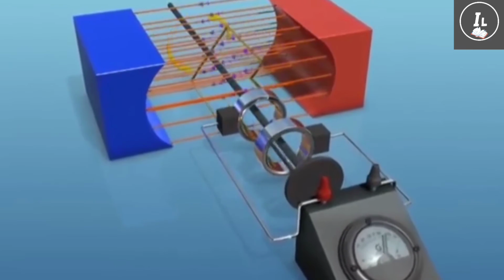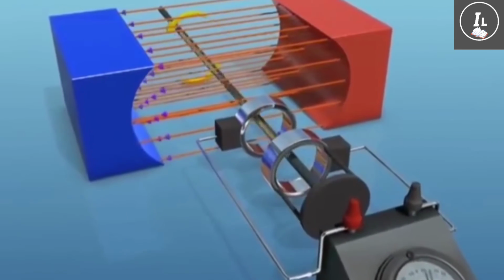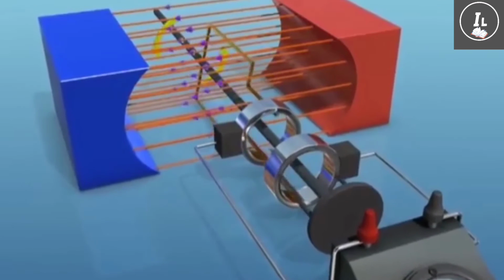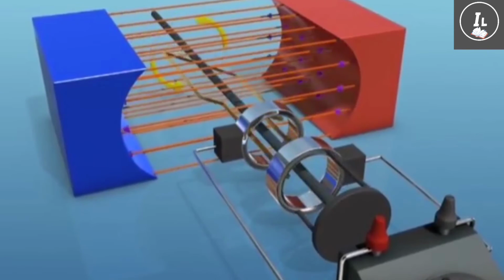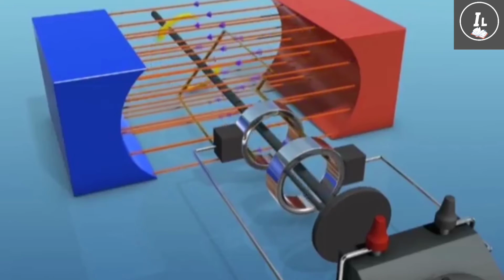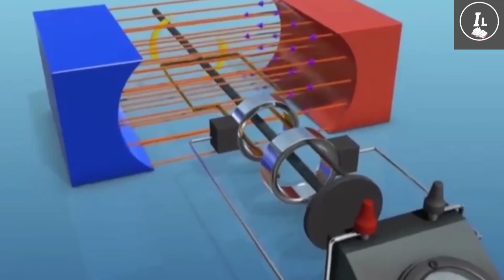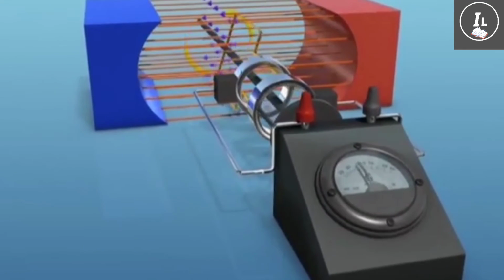This in turn induces an electric current in the coil, as the 2 ends of armature are connected to an external circuit. An electric current starts flowing through it. The current is detected by the galvanometer connected in the external circuit. Due to change in the relative position of the armature coil, the direction of the current flowing in each arm of the armature coil keeps on changing, and hence the current so obtained is alternating current.